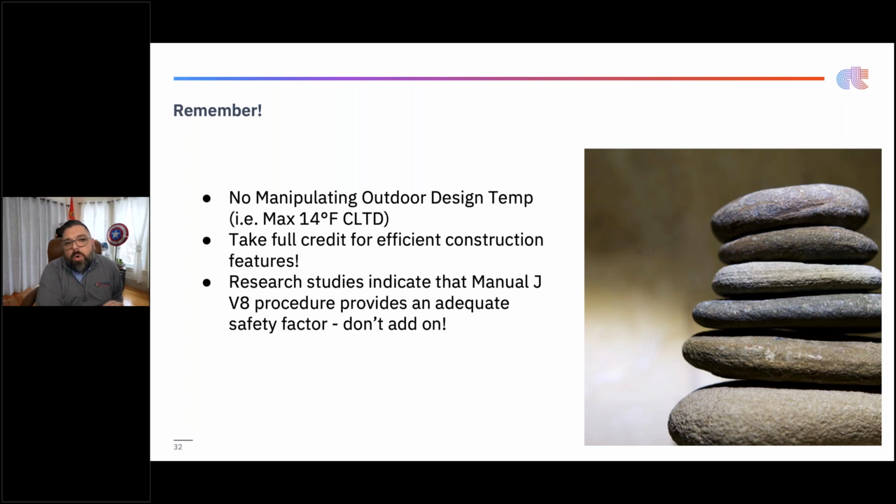And if you didn't know, at the beginning I told you I've been teaching this for about 15 years. I was very fortunate to be taught by Hank Rakowski, who wrote the manuals at ACCA. He was the PE that's on the front of every book. He actually said, because you have to stop the rounding and the decimals at some point, that there's about 20% of oversizing built into Manual J software, even on the most aggressive load calc.